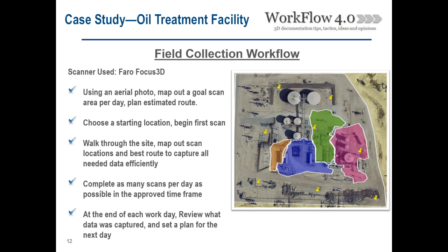As the scanner is going, we'll walk through the site and map out the scan locations and the best route to make sure we capture all the data that's needed. As you saw in those previous pictures, there's a lot of things to capture, and if you don't have the correct and enough setups, you may miss some critical data.